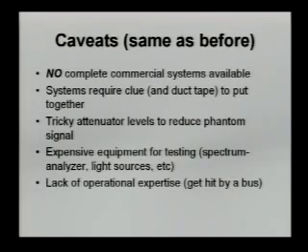If the fiber or the splices have significant internal reflection, you may get your own signal reflected back, and you would get a link to yourself, and then your port will get disabled because it will detect link. So you have to attenuate the signal to prevent this from happening.